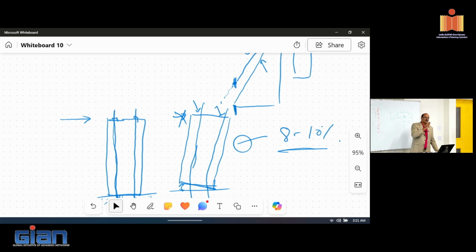So the reason this was a concern up until recent times is the pre-stressing technology, right? Can you rely on the quality of the pre-stressing anchorage so that you don't lose the strand? If one of the strands goes away, obviously you lost the connection completely.